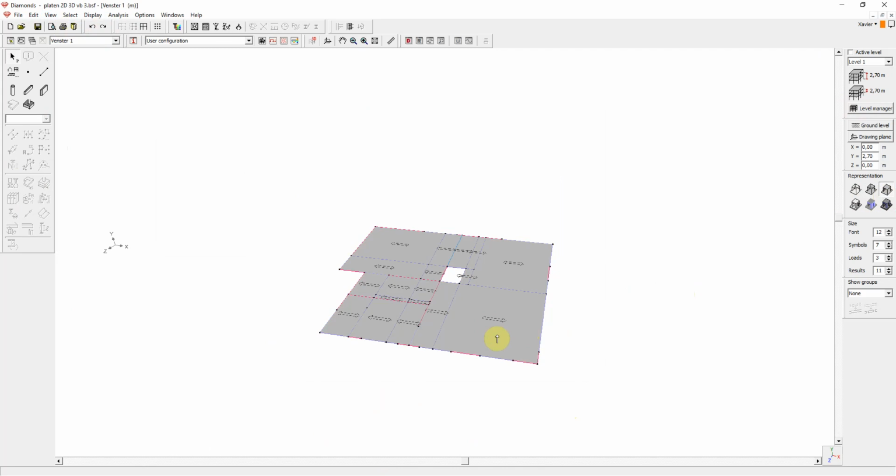In this model, for my convenience, I have assigned a layer, a design type, to the lines that need to be turned into walls. So these are the pink ones. And I select the plate with the control button, and holding the shift button down together with the control button, I will additionally select these pink lines. And I will also select this point, and I'm holding only the shift button down right now, together with this point, because I want them to be turned into columns.